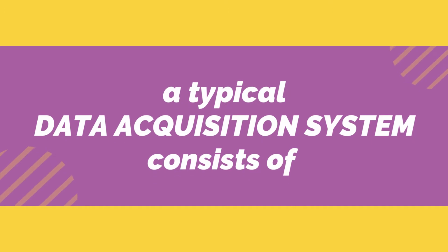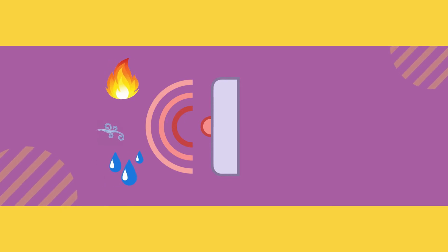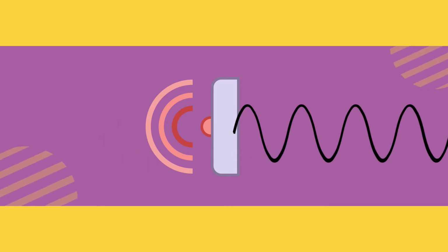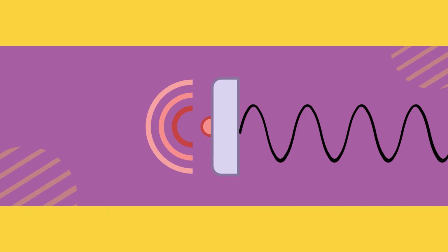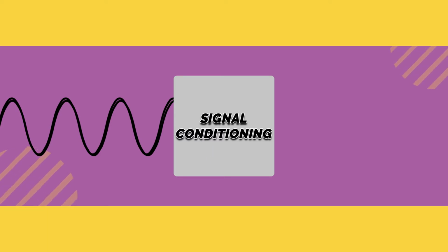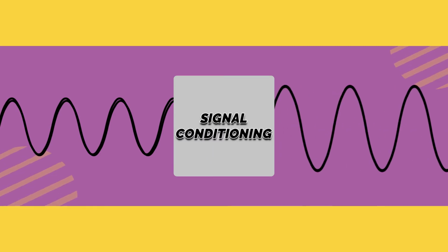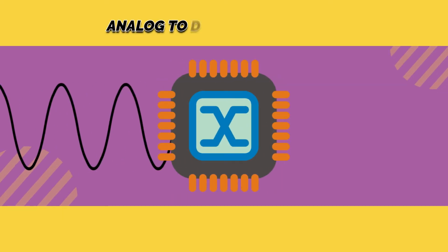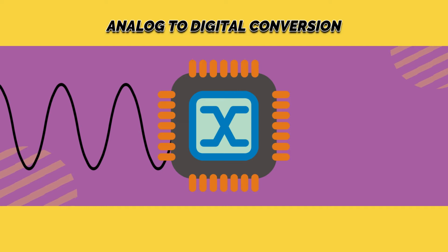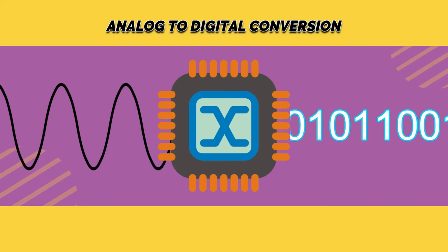A typical data acquisition system includes a sensor that measures physical parameters like humidity, temperature, pressure, and flow, and outputs a quantifiable electrical signal depending on the type of sensor used. The signals then undergo a signal conditioning process whereby the raw signals from the sensor are amplified depending on the line level requirements of the system and filtered to reduce unwanted frequencies. The clean analog signals from the signal conditioning will be digitized. The digital signals can be processed by a computer and stored for future analysis.